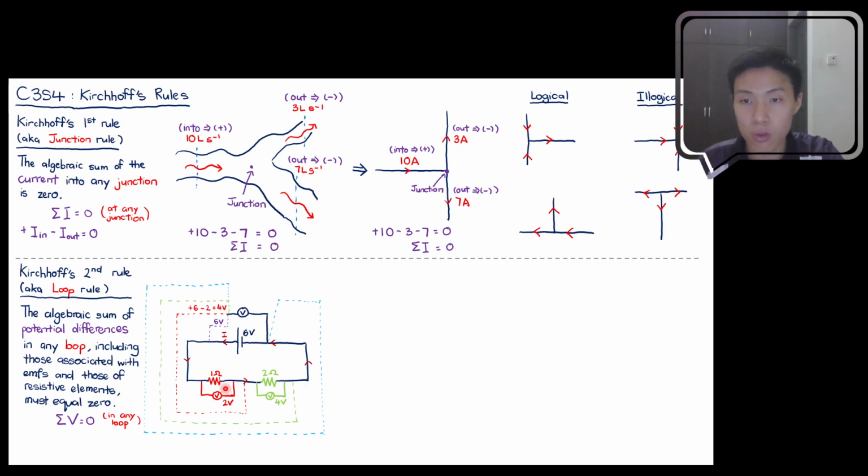Just now you initially lost 2 joule energy, coming out with 4 joule energy, but now you have 4 joule energy, you pass through this resistor, giving out all 4 joule energy to the 2 ohm resistor. So you come out from this 2 ohm resistor with 0 energy left. Okay, a 1 coulomb charge receives 6 joule from the battery, loses 2 joule to the 1 ohm resistor, followed by losing 4 joule to the 2 ohm resistor. 4 joule is the remaining energy left, so all 4 joule will be given to the 2 ohm resistor, resulting in you coming out with 0 joule energy.